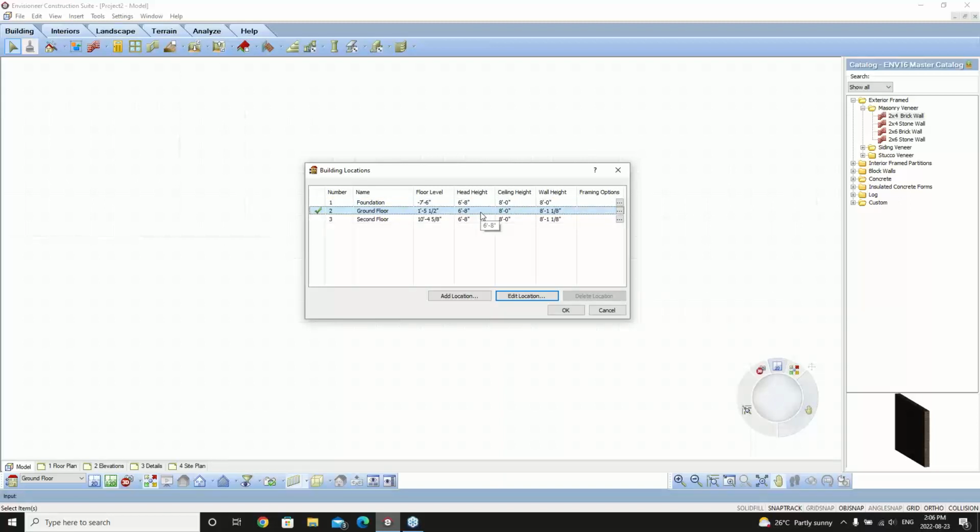In your drawing file, you can select those individual openings, ceilings, and walls, and you can adjust their property so that they sit a bit higher by either elevating them or adjusting the wall heights. So again, whatever the majority is, make that the value here. And again, that will be true for all of your different locations.